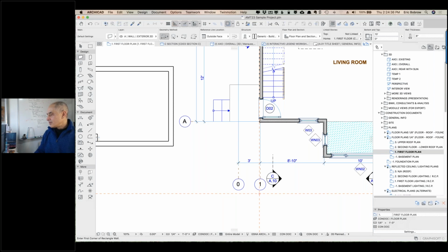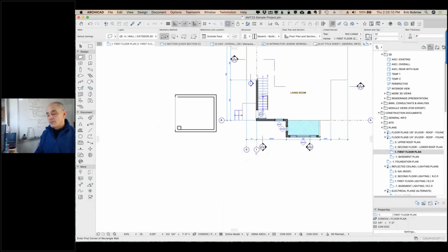Okay. Maria says ARCHICAD layer is also used to copy paste between files to avoid importing the new layer. That's a good workflow suggestion. I mentioned earlier how if you bring something in from another file and it's on a layer that's not part of your working environment, you may then have this extra layer to deal with. One way to avoid that is, before you copy it from the other file, to put the elements onto the ARCHICAD layer. Now here's a little tip, a little trick.